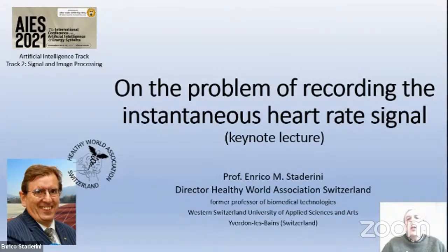Now, most signals are continuous, and they are continuous both in magnitude and in time. For example, if you consider the acoustical pressure on a microphone, of course, the acoustical pressure on a microphone is a continuous signal in the sense that the value of this pressure can assume any possible value on a range of values. And if signals are not continuous, we say they are digital in the sense that the magnitude of the signal can only assume one or two values or a finite set of different values.